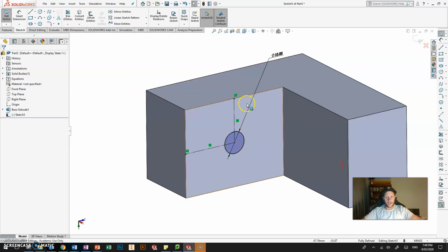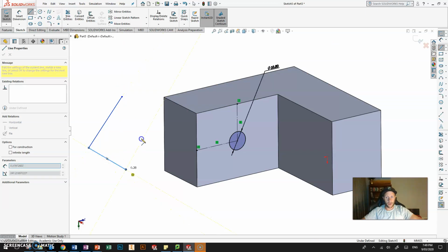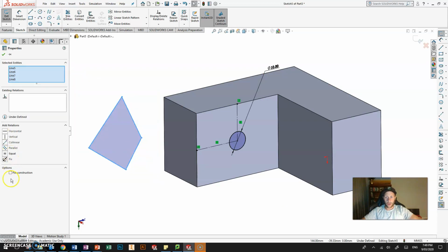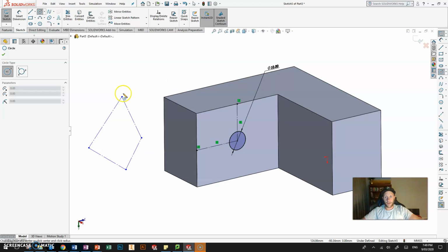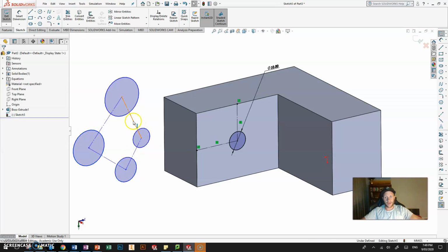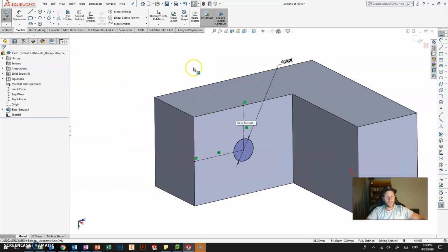So the gist of what I've just shown you is that you can create any form of geometry. So I can create something out here, click lines, and I can use that as reference. So if I highlight, click and drag a window, I can make all of these lines construction lines, and then I can use the endpoints of this. So I can draw a circle, I can do multiple circles around here, and these are all constrained or joined to the ends of those points. So if I move them, the circle sticks to it. Cool. All right, just delete those. That was just for discussion.